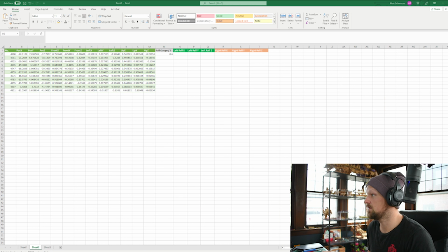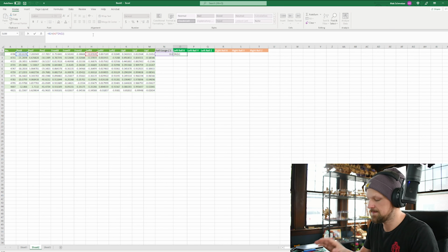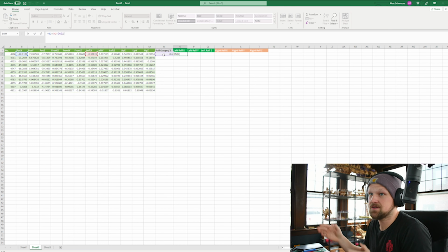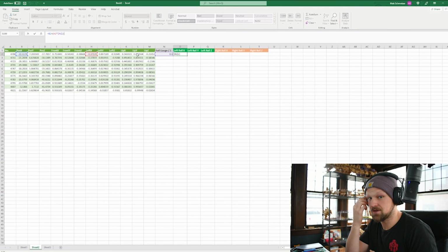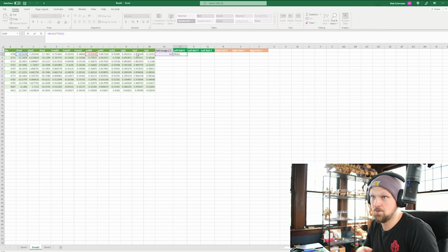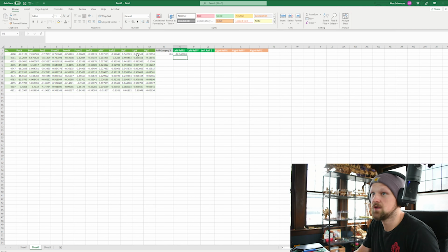So for the left rail, I'm going to go kind of fast, and if you miss anything, just pause the video and take a look at what we're doing here. What we're doing, from that image, is position X plus, in parentheses, our left X multiplied by our rail gauge, which is the magnitude. Remember, this left X and Y is basically a unit vector, or a direction. And we have to do that for the Y and the Z too, to get our entire point. Then we just take that across, as you can see in the equation, and bring it all the way down.